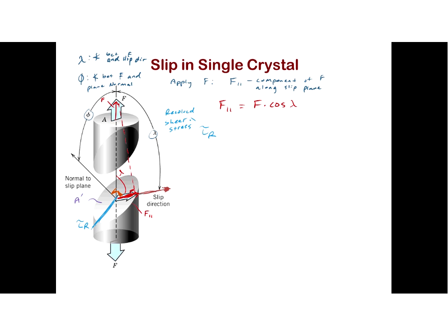Okay, so the shear stress happens along that direction, and shear stress, as it was defined earlier in the chapter, is still just equal to the force applied parallel to the area, F parallel, divided by the cross-sectional area of the plane. What's the cross-sectional area of the plane? Is it A? Or is it A prime? It's A prime. It's the ellipse, right? So now what we need to do is find what A prime is. So what does A prime equal? And what we can do is describe this in terms of A.